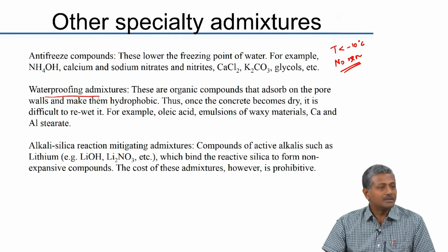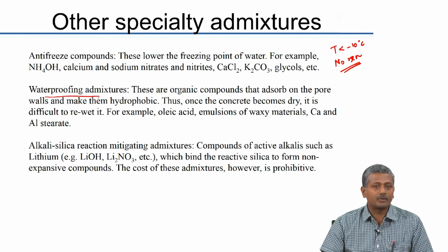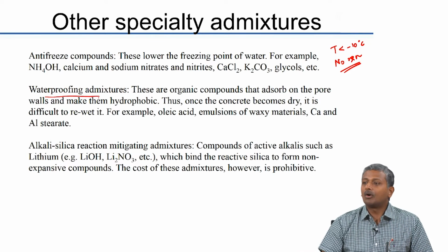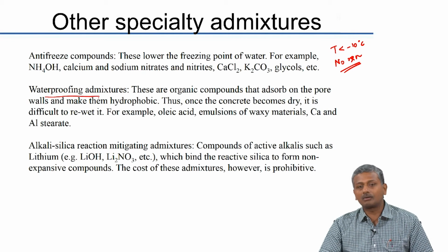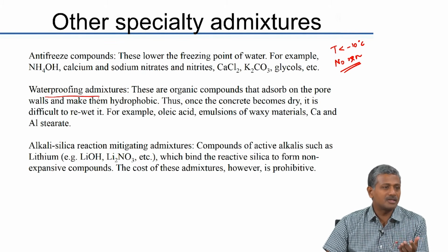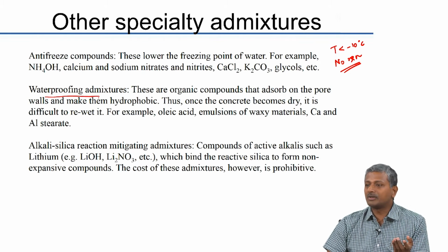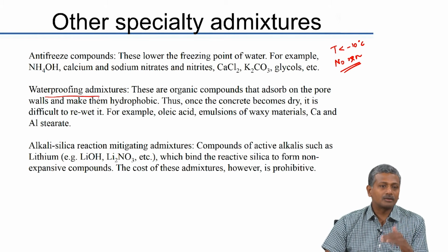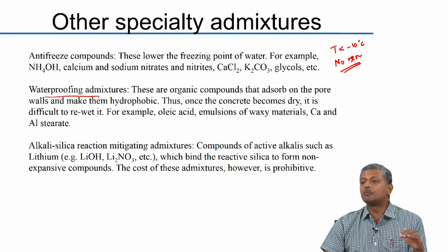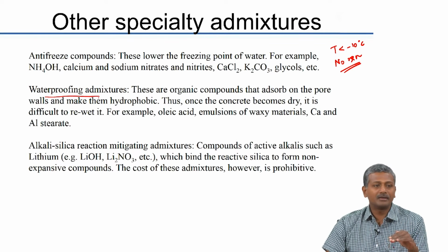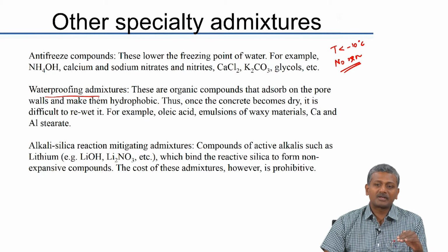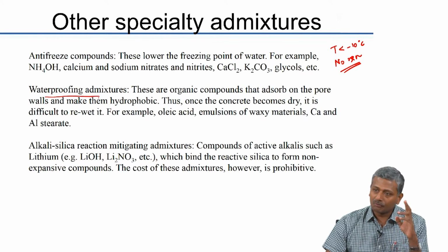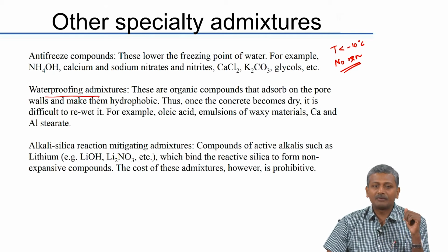They are actually waterproofing systems that can be applied on the surface of the concrete, or as layers between the concrete, and so on. You have learnt about some of these in your detailing. For example, when you design the flooring of any building, you also have a layer called damp proof course, right, if you remember that. And there are also specific designs of the waterproofing for the roofing that we do.